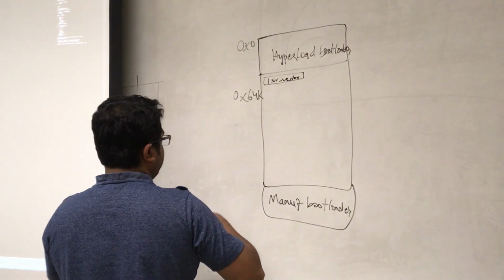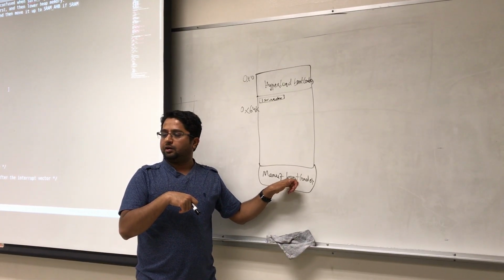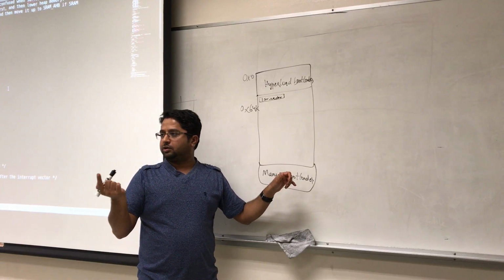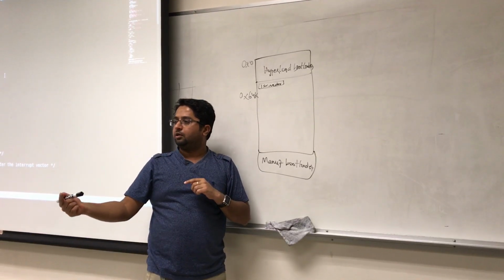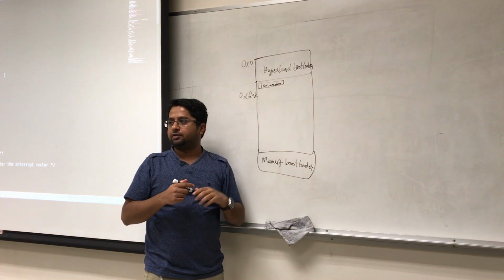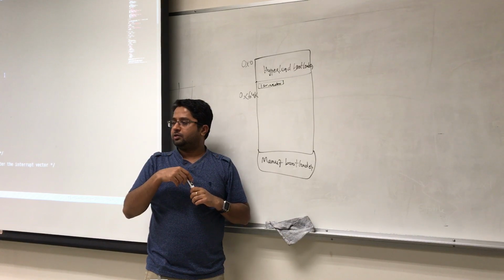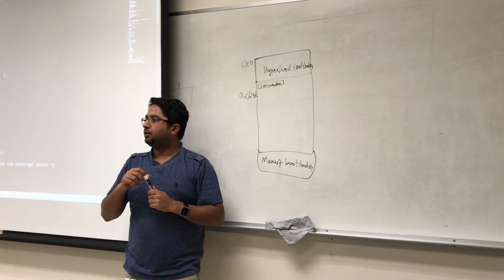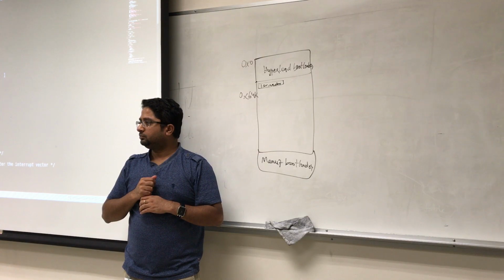Yeah. So your manufacturer bootloader will sit somewhere in the memory, and then the first time you load your microcontroller, the hyperload bootloader is what takes the program from your laptop to the microcontroller, and then it starts loading from the address 64K. That's what the comment in loader.ld says. So the first thing that it tries to load up is where your interrupt service routine is. So is this file being read by hyperloader? Is that what this is for?